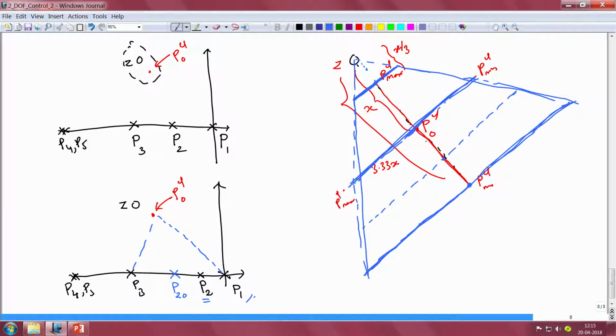Likewise, for a particular pole location, namely at s equal to minus 2, when the plant's gain changes, the closed loop pole will vary along this particular straight line which I am highlighting here with blue color. Likewise, when the plant pole is at s equal to 0 and its gain increases by a factor of 3 or reduces to 30% of its nominal value, the closed loop pole is going to vary along the straight line that I am highlighting now. So these four straight lines form the edges of the region within which the closed loop pole would vary when the plant's gain and pole change.